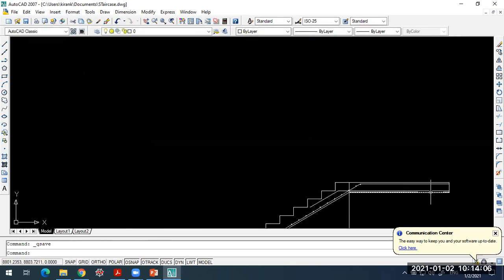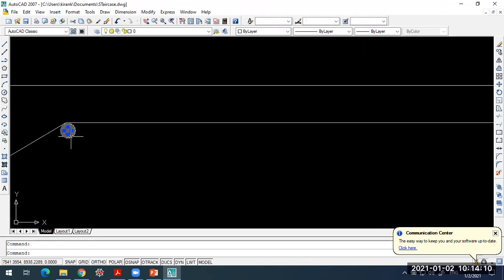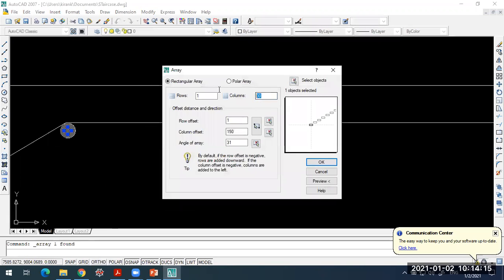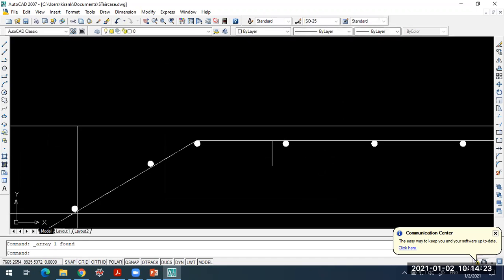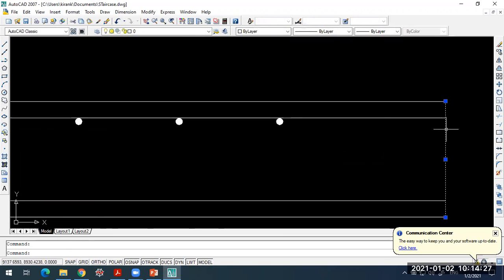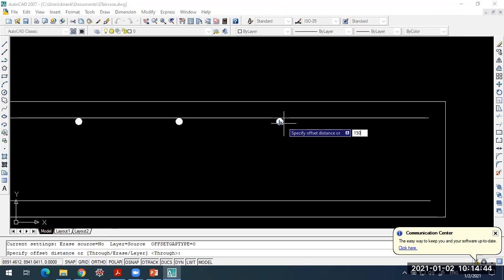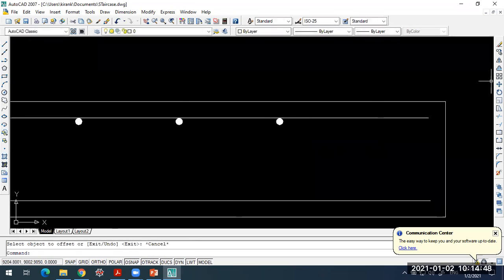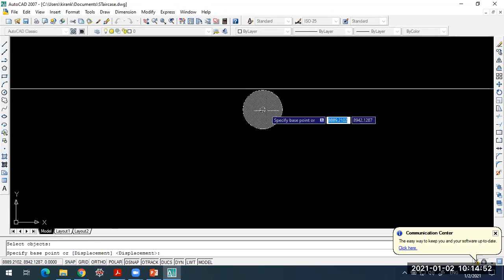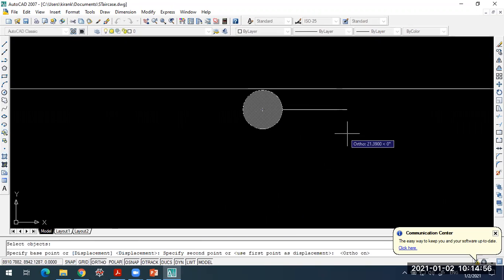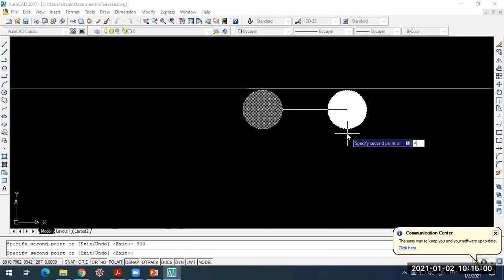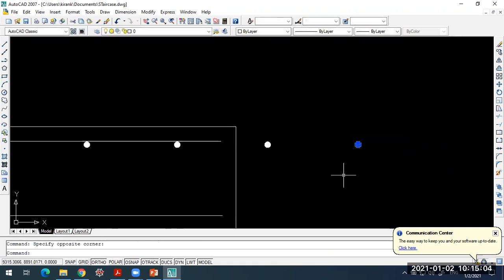This is it. Then again for the slab, we'll choose it as 10. Okay, choose that one. Right. This will stop it. We'll offset through 150. Just one or two objects. Okay. Copy. Center point. Auto on 150, 300, 450. That should be enough. Okay. So this is sufficient.